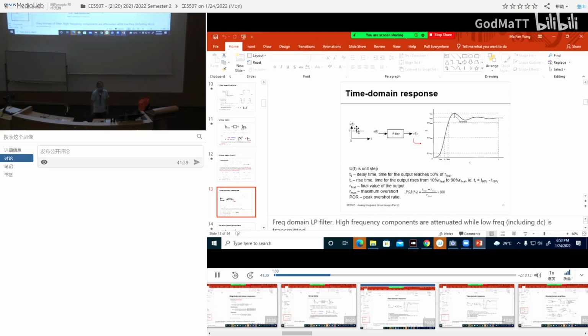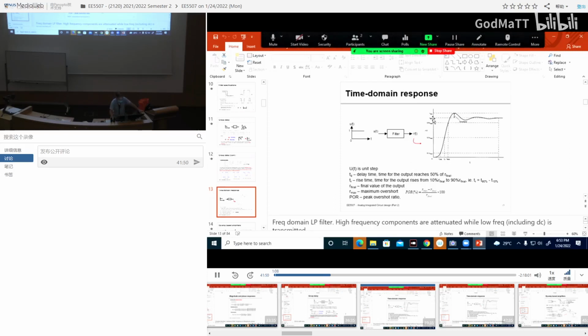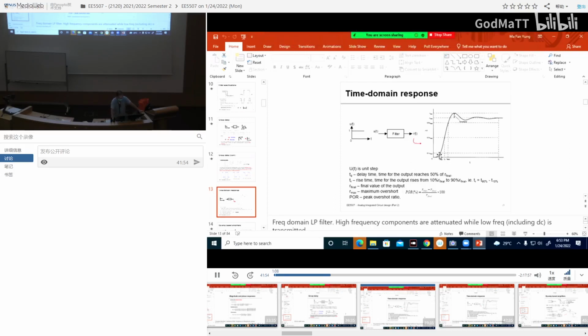That's why your filter got problem. Your filter is a low pass filter, so what happened to all the high frequency part? Got filtered out. So the filter cannot pass the vertical edge. That's why the filter can only slowly go up. Basically, any sharp edge means there is high frequency component. That's the simplest way to understand.